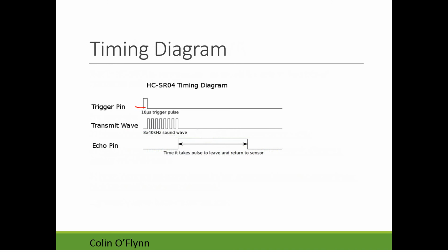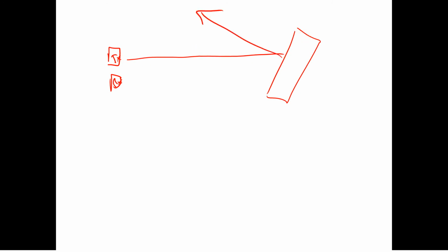One thing is that you have your system here, the transmit and receive. You might want to do multiple tests of an object, because obviously if your robot is at a weird angle, it is possible that you could transmit and it doesn't see the echo if the echo goes off this way. They have a pretty wide field of view, so most reasonable objects it'll detect, but if you're at just the wrong angle, it just won't detect it.